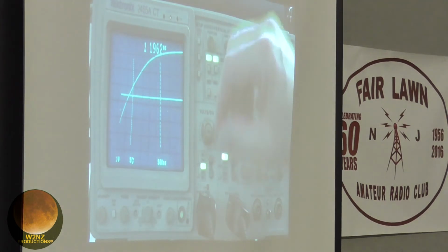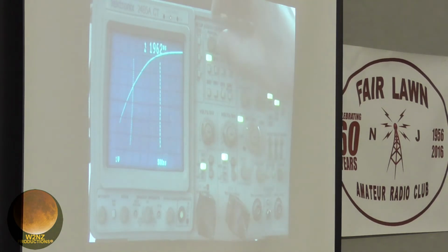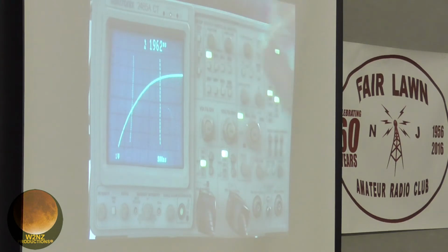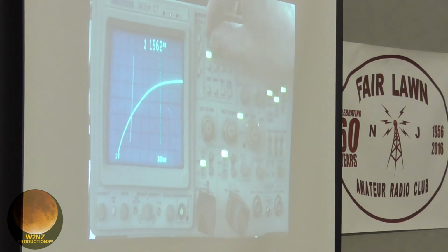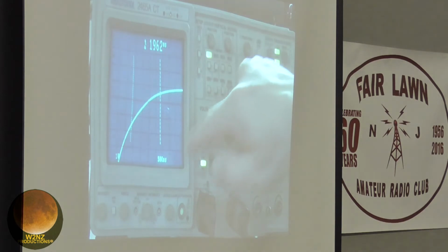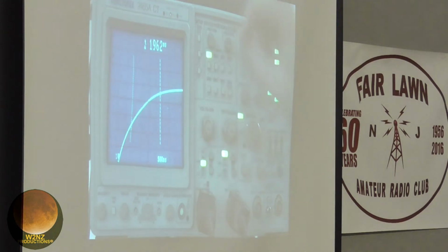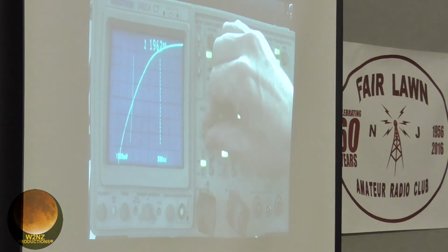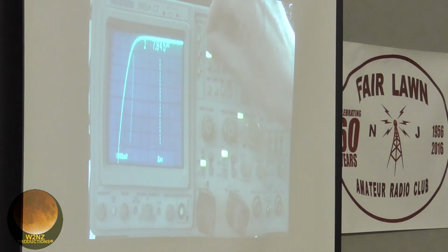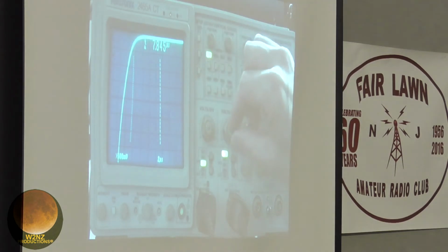Now I can actually see, if we ignore channel 2 and turn that off, the baseline right down here at the bottom. We put it at the bottom of the screen because this scope gives me 8 vertical divisions total. You can see them, 1, 2, 3, 4. Let's adjust the scale so that I'm going the full 8 divisions, from the bottom to the full 8 divisions.